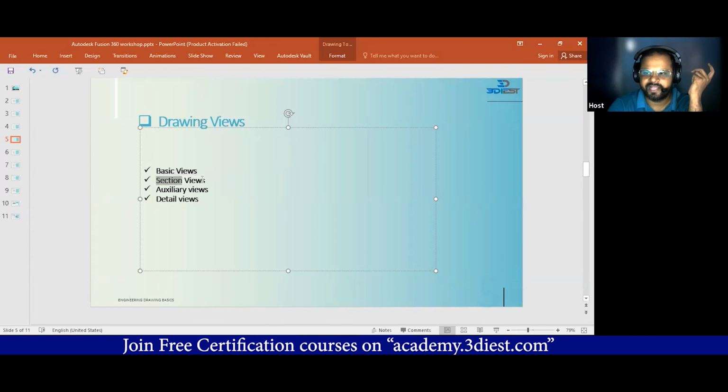Then the section views: if you want to see a section at a particular plane, you can take that, and that is called a section view. We'll learn how we can create these views inside Fusion 360. Then we'll also talk about auxiliary views, like if you want to take views along a particular plane that is inclined at a certain angle, so that we can also consider it in our drawing. That is called an auxiliary view.